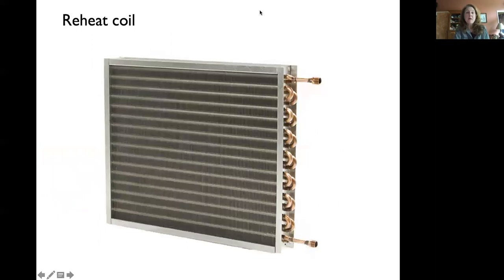And this is a picture of what a reheat coil is going to look like. And you can see these in Worcester. So when we get back to Worcester, which we're looking forward to at some point, in any of the classrooms, you look up at the ducts, and right where the duct comes into the room, you'll see the edges of these coils sticking out. And what you're seeing there is a terminal reheat coil. And that's where you can add more hot water to supply additional heat to a room to match its thermostat setting.